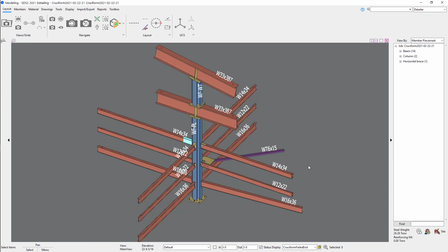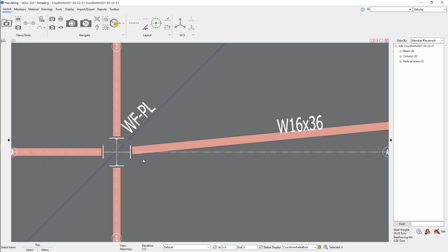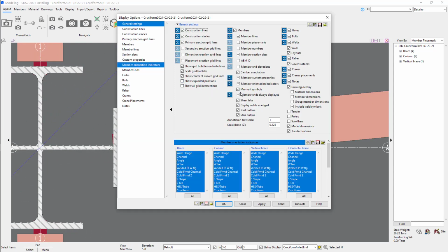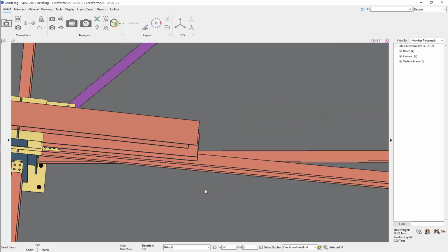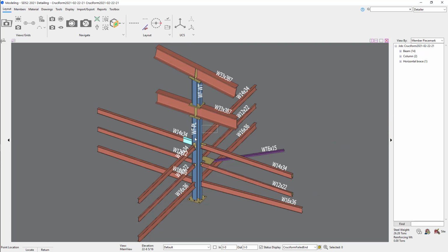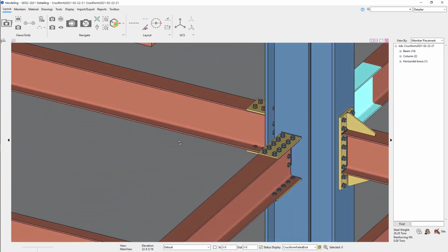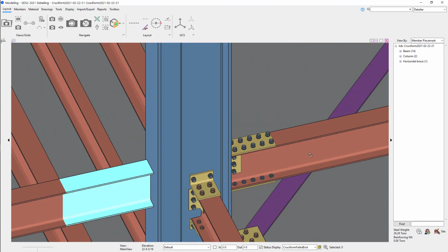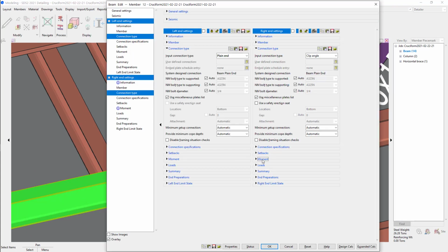We do not support skewed moment connections, but we will support skewed connections so long as the material lands on the flange. A few points I need to mention. We do not support the design for the web stresses. So, if you want a moment connection to a column without forcing the connection, simply turn off the design doublers and stiffeners.